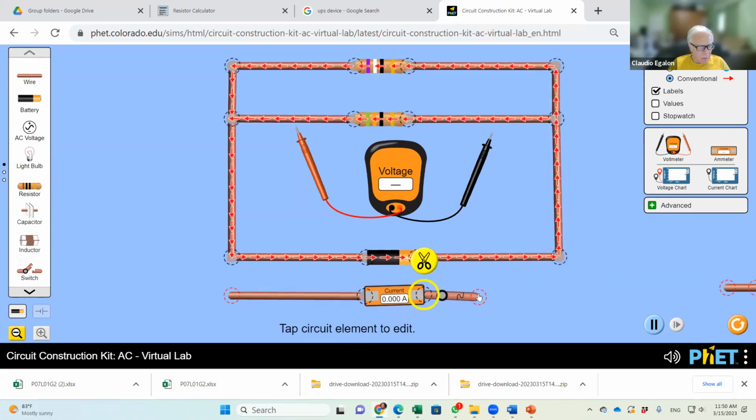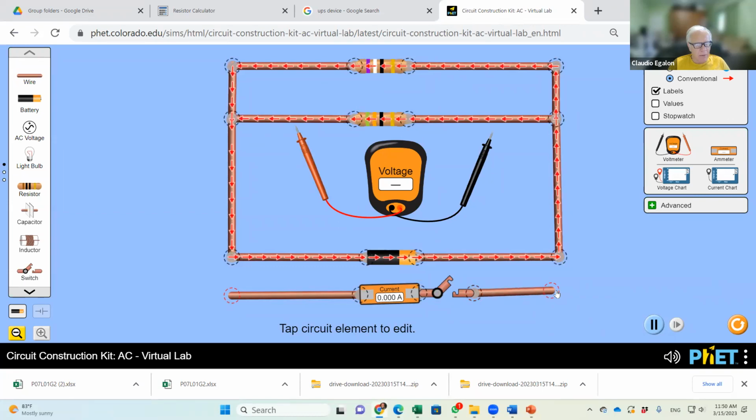You damage what we call the fuse, that protects the device. Fuses are very inexpensive devices that are capable of protecting very expensive devices. That's what fuses are. Right here, okay. I am connecting my, I'm not supposed to be doing that, remember? Ammeters can never be connected in parallel. And now I'm going to watch the measurement, what's going to happen.